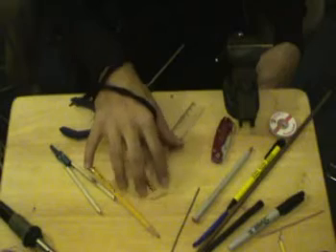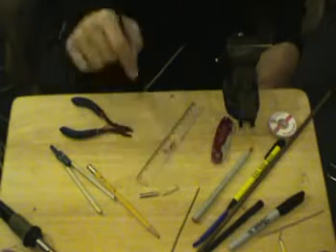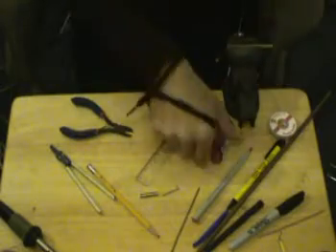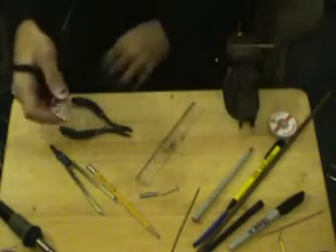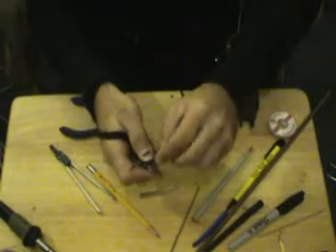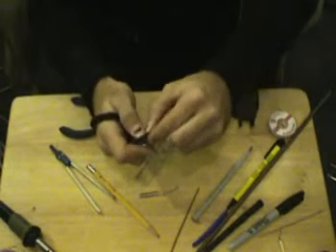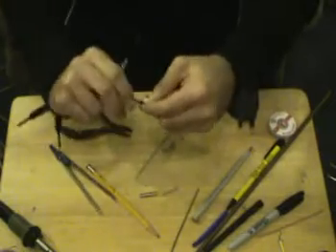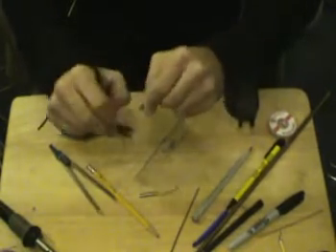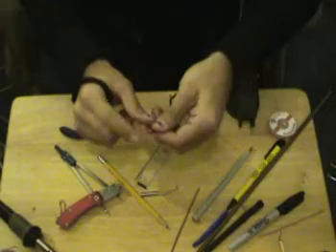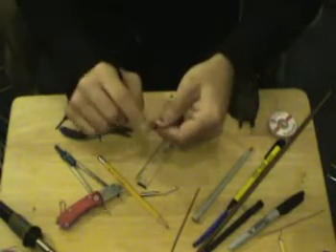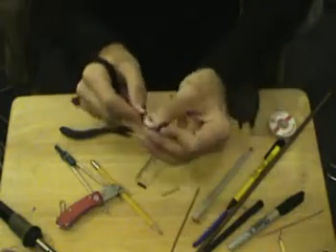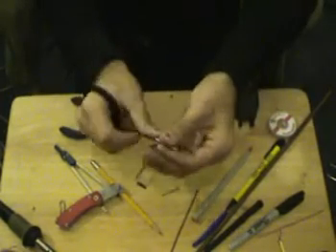Okay, so we got the tube end, and we've got the little nubbin end. So, let's go ahead and get this on the coax. Got a little razor blade here, and I'm just going to pull off this outer insulator to reveal the shield, trying very carefully not to pierce the shield, or even the center conductor, and then just peel the shield. Well, actually, first thing you got to do, sorry, I always forget to do this. Go ahead and put your collar on first.